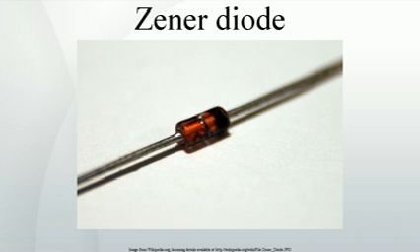Shunt regulators are simple, but the requirements that the ballast resistor be small enough to avoid excessive voltage drop during worst-case operation, low input voltage concurrent with high load current, tends to leave a lot of current flowing in the diode much of the time, making for a fairly wasteful regulator with high quiescent power dissipation, only suitable for smaller loads. These devices are also encountered, typically in series with a base emitter junction, in transistor stages where selective choice